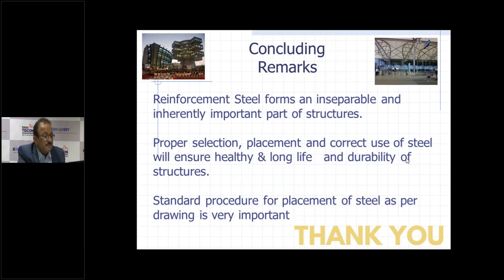So that is why couplers are very commonly used. Then Hemant Wadalkar is asking, we should go with stainless steel reinforcement which has lower life cycle cost for the structure. But it is very expensive. Some few sites have tried this just as an R&D matter. Commercially it's not viable. If you have a lot of money and you don't care for the expenses, I don't mind you going for stainless steel reinforcement bar.